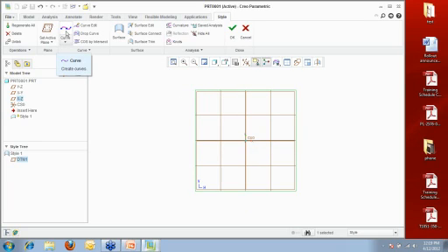Now, these curves are all just spline based. So if you think of them as a spline, that's essentially what you're creating right here. You have a separation between 2D and 3D splines. They're called planar curves and then non-planar curves. Now, also what you have in the drop-down is arc and circle. I forgot which Wildfire it was, I think in Wildfire 3 they introduced the arc and the circle command within ISDX because not everybody just wants to create splines. You might want to create arcs and circles.